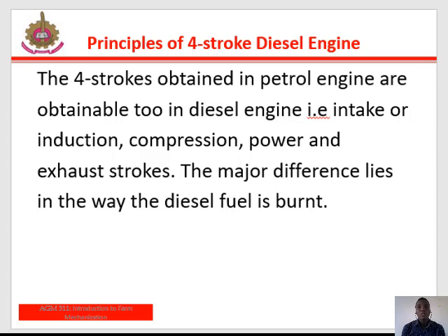Next we are going to be looking at the principle of the 4-stroke diesel engine. The 4 strokes obtained in the petrol engine are obtainable too in the diesel engine. That is the intake or induction stroke, the compression stroke, the power stroke, and the exhaust stroke. The major difference lies in the way the diesel fuel is burned. In the intake stroke, the inlet valve opens while the exhaust valve remains closed. Air only is supplied into the combustion chamber, forcing the piston downwards.